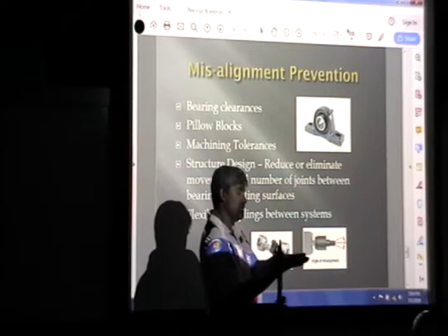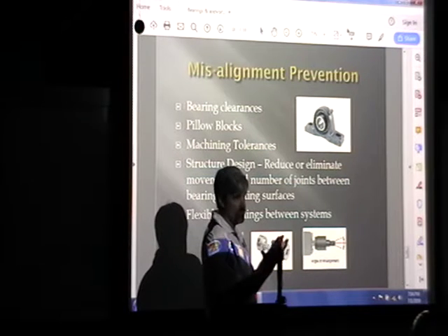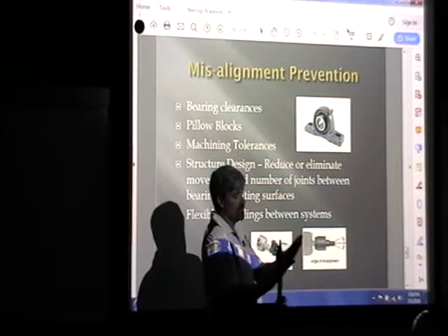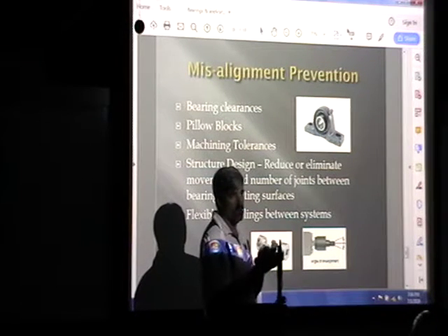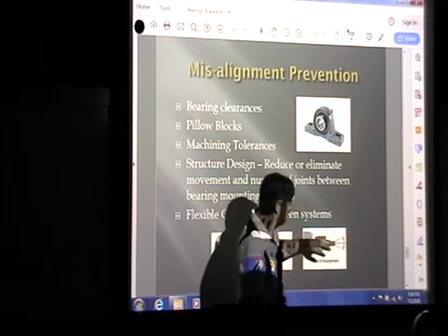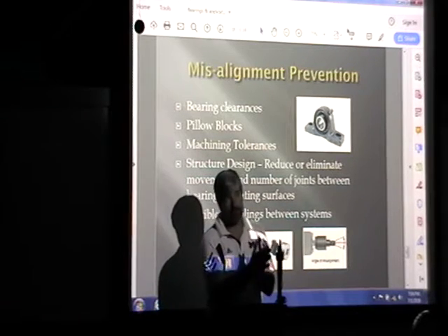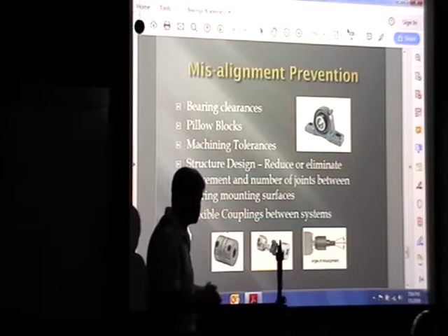What that is, is two plates, because it's just a compression cylinder. The cylinder presses and pulls. So now you've just got two plates. As that goes down, those slide a little bit between each other to keep the systems from locking up. But it goes back to the same topic. You've got a fixed alignment load system and a fixed alignment actuator system, and you have to keep those from locking up. So you use these misalignment couplers.